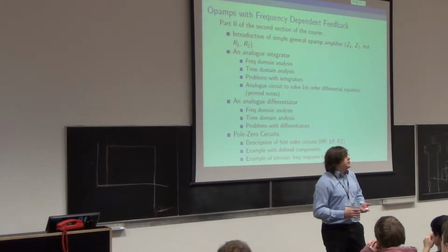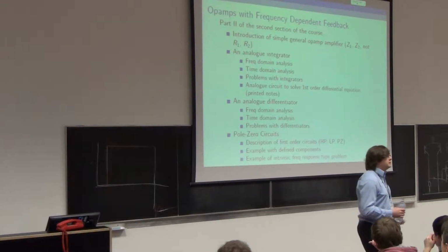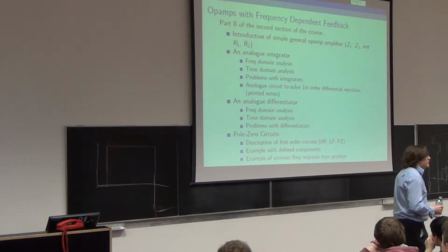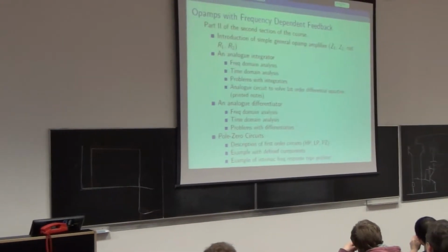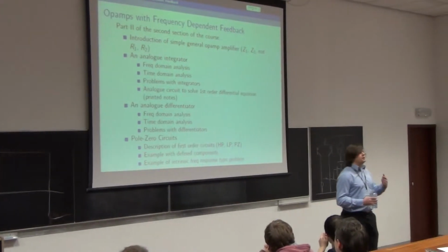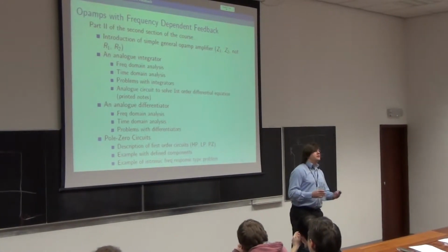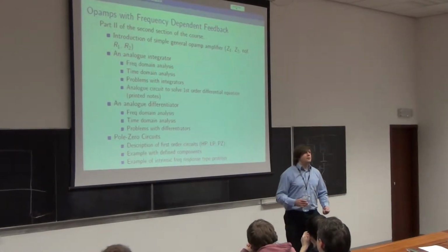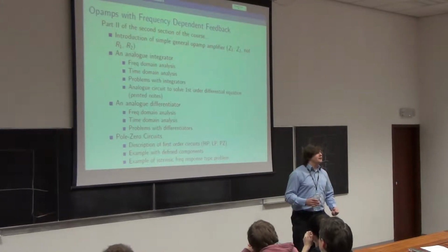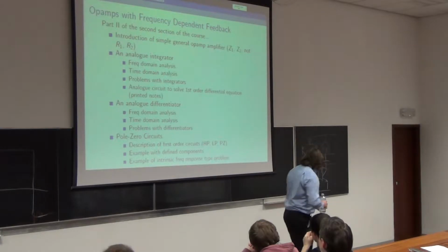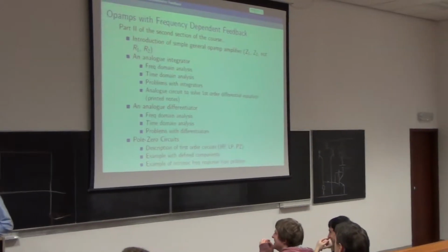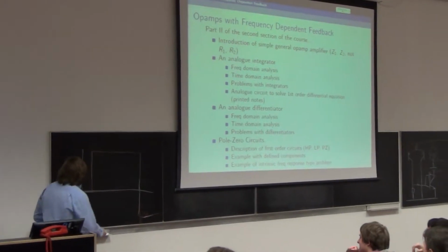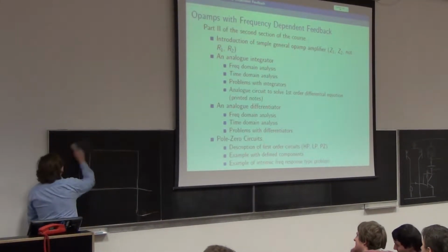And to make your life easy, and to make life easier for the person who uses this, it's going to be an IC, you want the pin they connect the photodiode to be at 0 volts. So when they put 5 volts on the other pin of the photodiode, they know it's biased at 5 volts. Happy with the situation so far? Can you see in your head the circuit that I'm talking about? You all need to get Google SketchUp for your brains so that we don't have to draw too many diagrams.